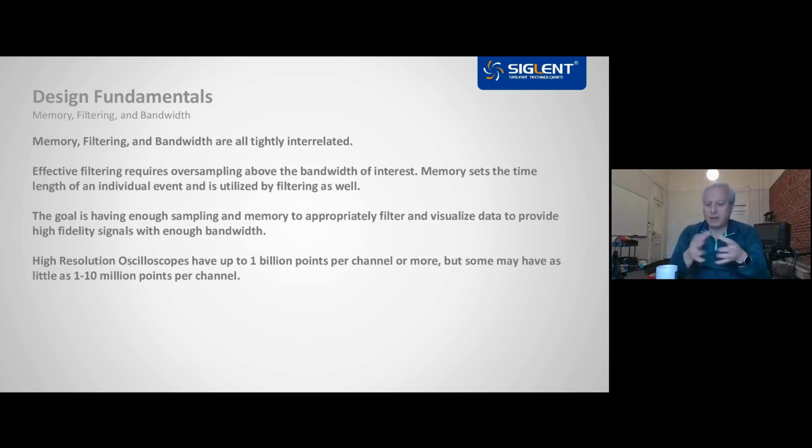This is effectively a type of boxcar filtering, where combining consecutive samples in groups allows us to artificially reduce the quantization error by estimating voltage levels between the actual bits. So these trade-offs create opportunities to improve and optimize noise and ultimately signal fidelity within a smaller bandwidth. Using this method effectively reduces the bandwidth along with the sampling reduction.